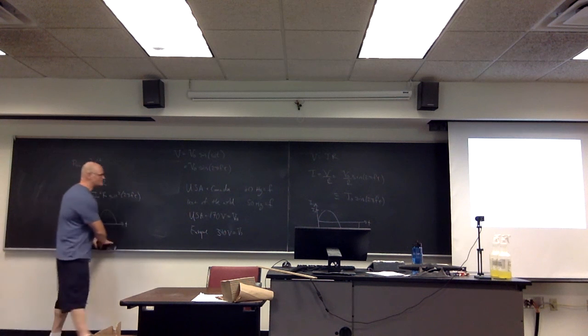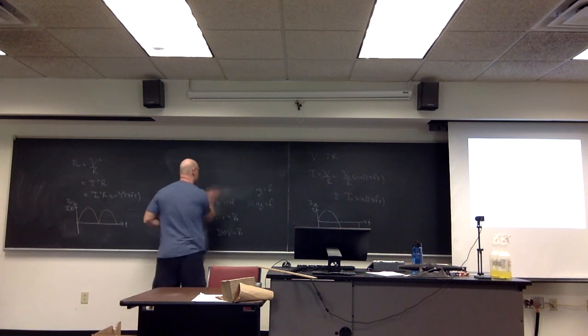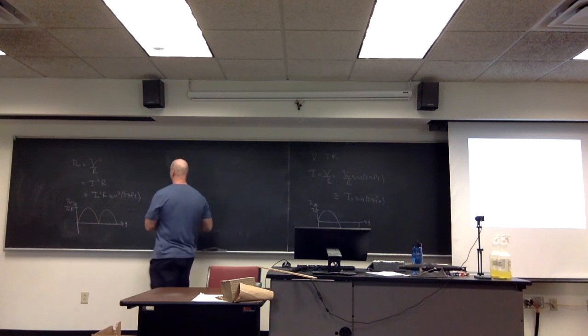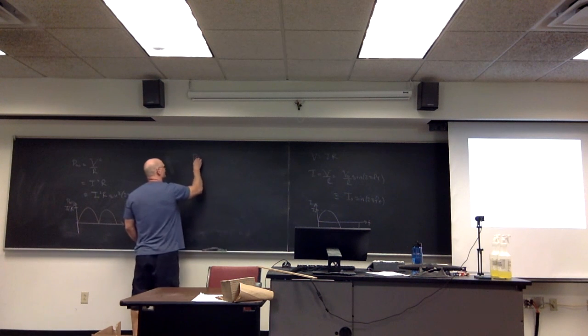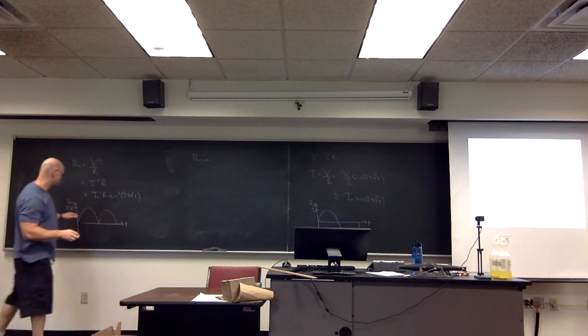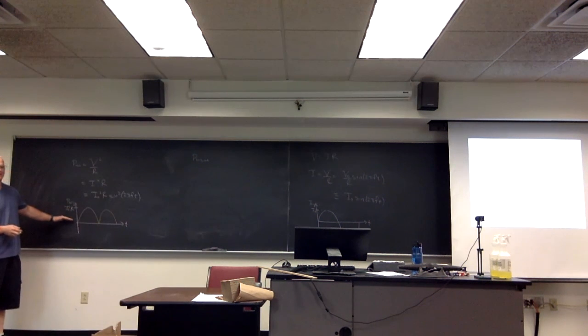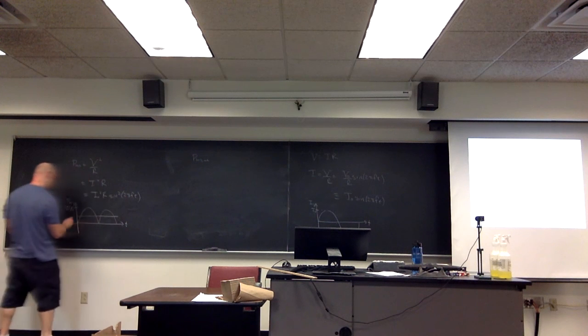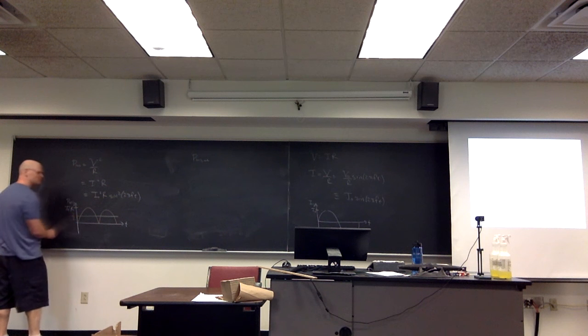So when we actually measure the power which is being lost, we measure its average value. The average value of the power being lost is equal to the average of the sine squared curve. The average of the sine squared curve is this location here, which is simply 1/2.